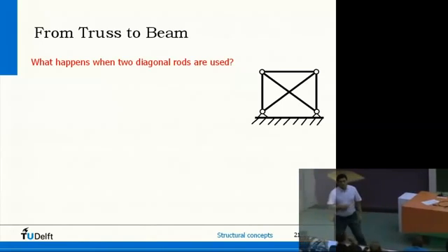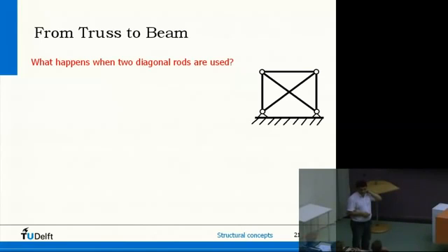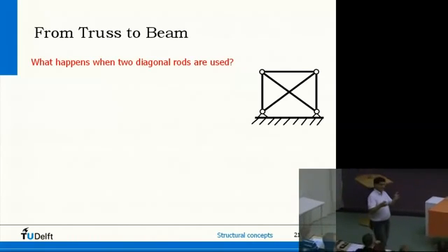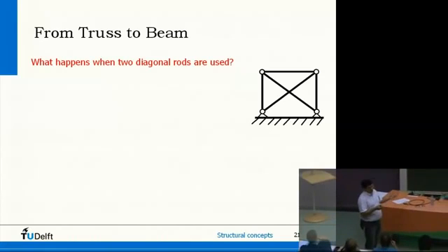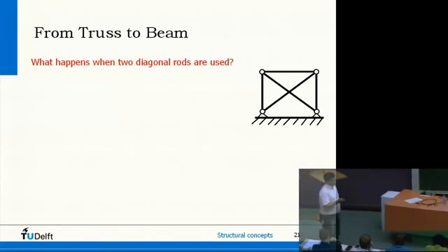Well, actually, you have two problems with that. First of all, indeed, the weight. You should say the weight here is too much, because you add an extra bar which is not useful. It's not adding something. And the second one is to get these two bars in the structure. One is okay, that's very easy, because then you have enough flexibility to put that bar in. But if you have to put in the other one, you also need a high accuracy, because otherwise it does not fit properly. So you make it yourself rather difficult to do so.